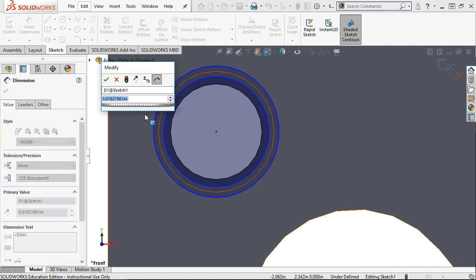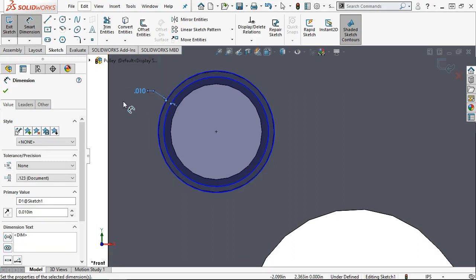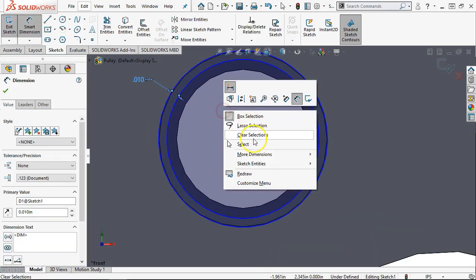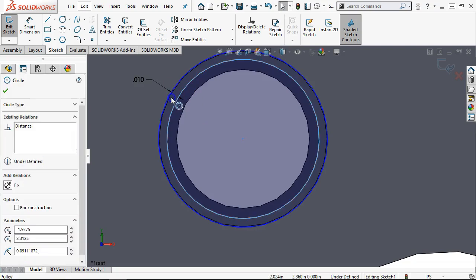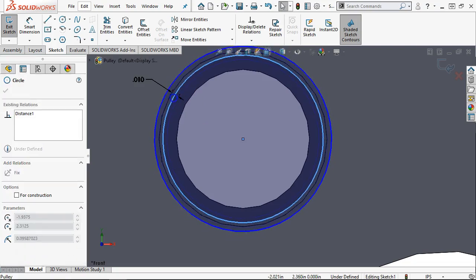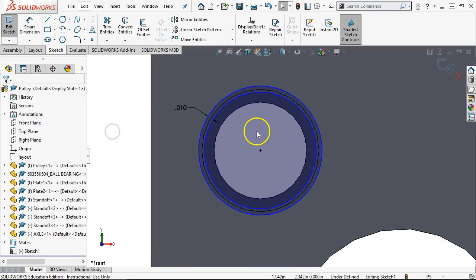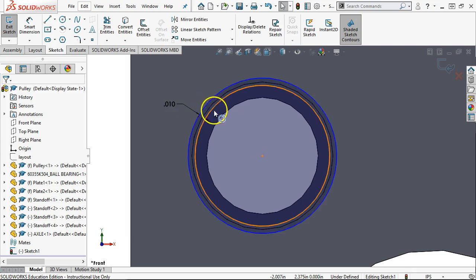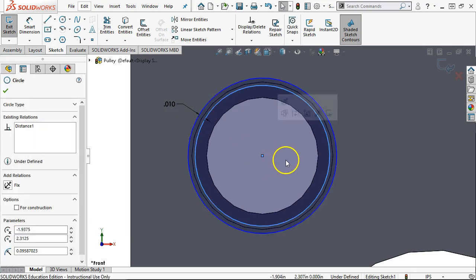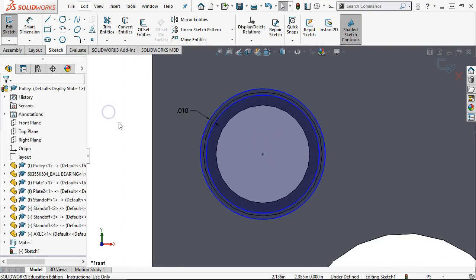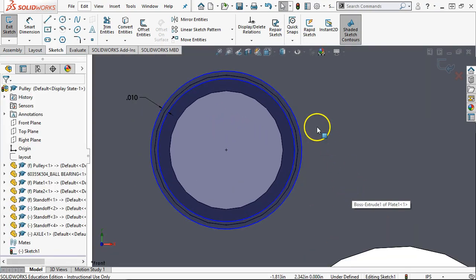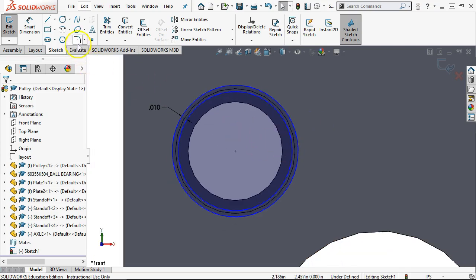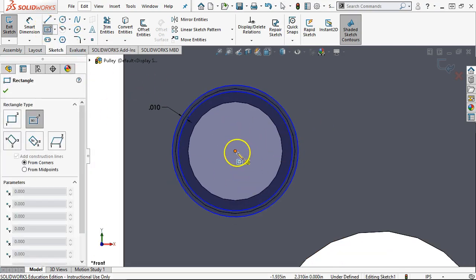So if we were doing cylindricity, we could say we have an envelope of, let's make it 10, so it's probably still visible. And I'm going to shift that just a little bit over the edge because I haven't really set a diameter for it yet. I would need to go from that edge 5,000ths because we're midline on the edge. And then for our plus or minus tolerance, I'm going to do the center rectangle.